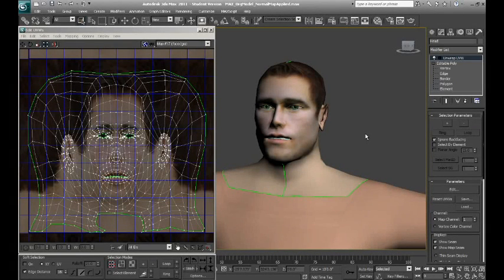In this lesson, we're going to talk about how to create and apply a normal map created in ZBrush using your high resolution mesh. Now, the first thing we want to do is make sure that we have our UVs laid out in a way where none of the UVs are actually overlapping. Here you can see that my ears are not appropriately laid out, so I'm going to expect some wonkiness with the ZBrush tool, but you do not want to do this. You want to go ahead and lay out everything so the UVs are not overlapping.